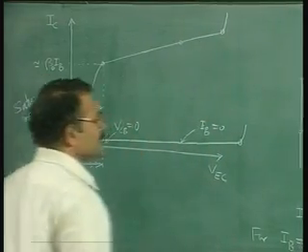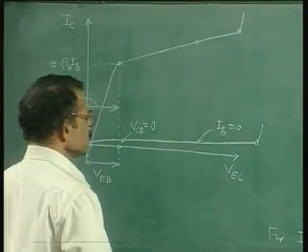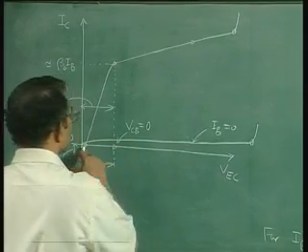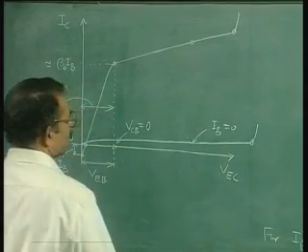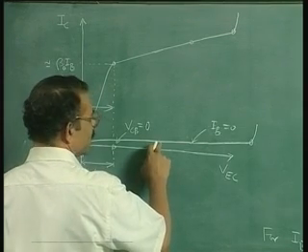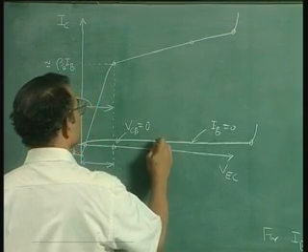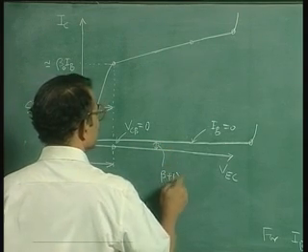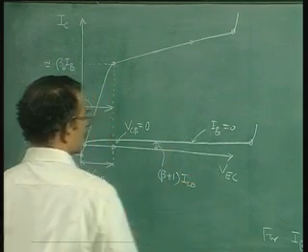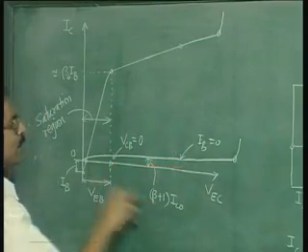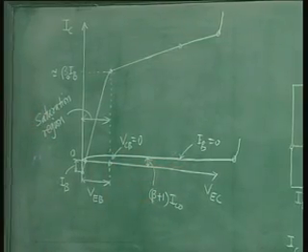This issue we will discuss separately, why this happens. Now we just want to plot this curve for IB equal to 0. So this value is beta plus 1 times IC naught, the value of the current here. There is a small slope here, it is not exactly flat because beta is changing with VEC.